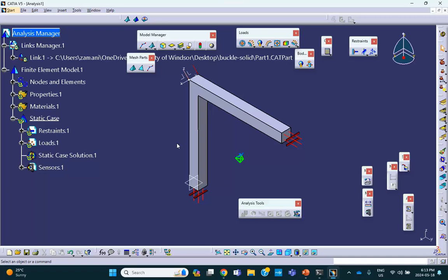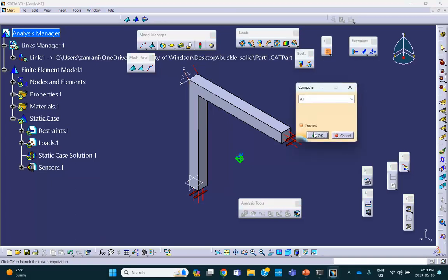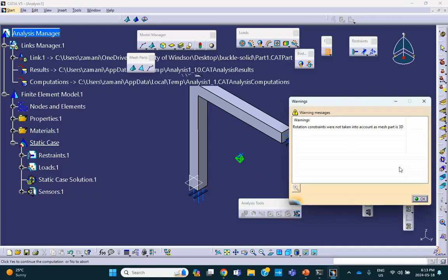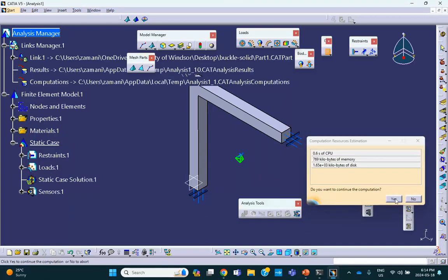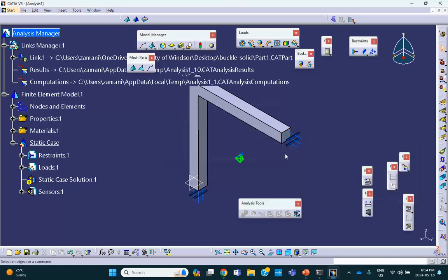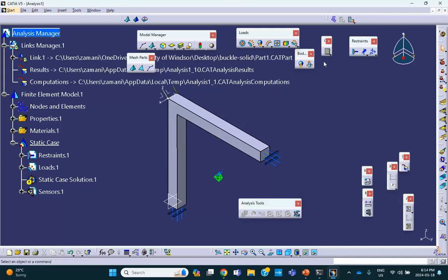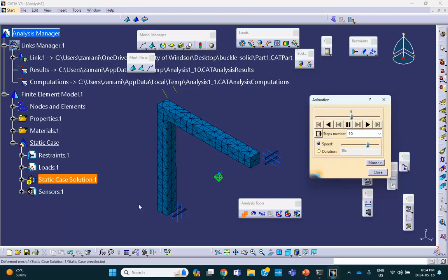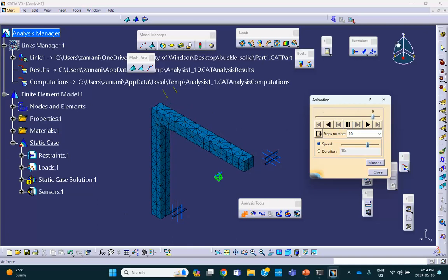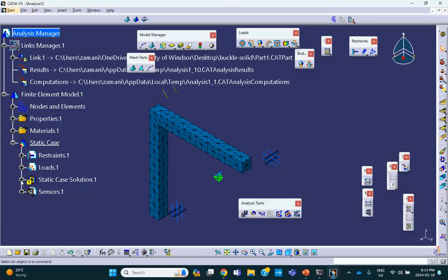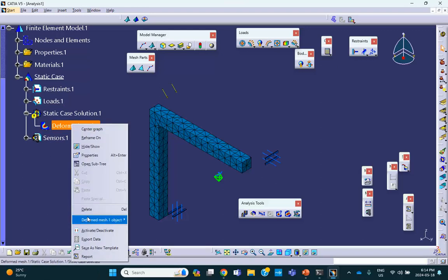And hopefully you can see why, but let's do it and find out that it bombs out, and then try to use our imagination and what you have learned in the past 2 weeks to figure out what's going on. Okay. The reason, if you don't know the reason, maybe Katia will tell you. Click on this deformation, you can see what happened. Because this whole thing is free to move as a rigid body along the direction X. You say, okay, no problem. Deactivate this plot. Let's prevent that rigid body motion.